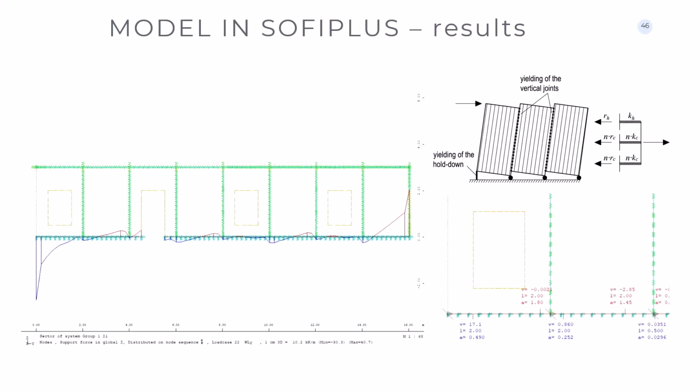Instead, here you have distributed forces, you know? And SOFiSTiK allows you to integrate this and give you, with respect to the exact point where they integrate, the total shear forces and the total tension forces and the total compression forces here. So with this number, this is the integration of this curve until a certain point, you can design your connection.